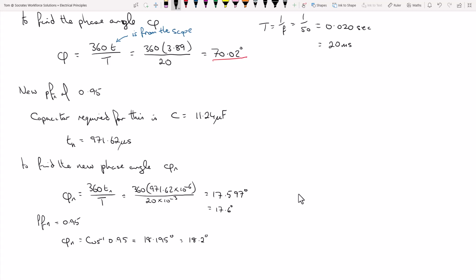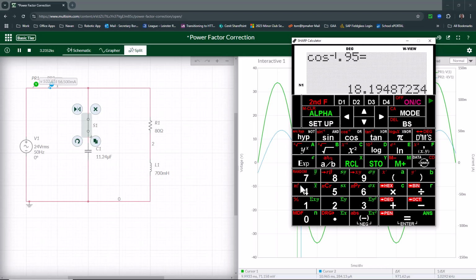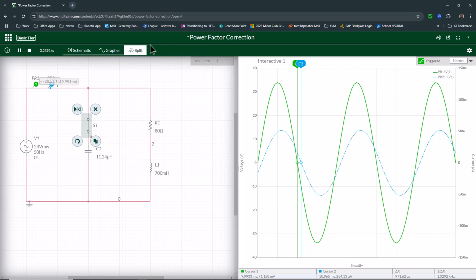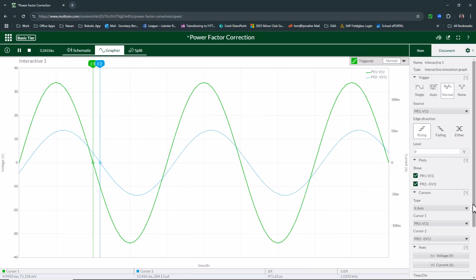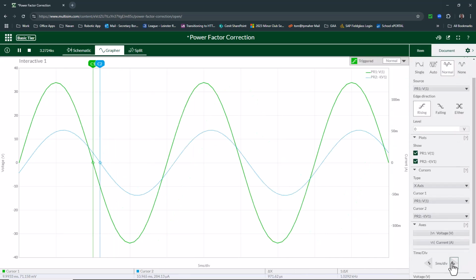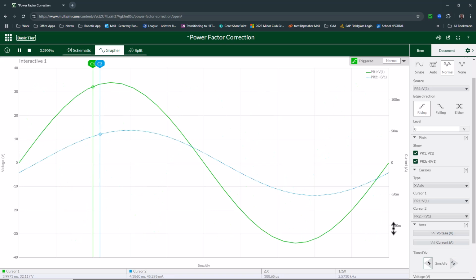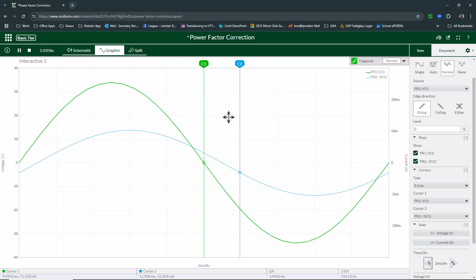Okay, what can we do to improve that a little bit? What we could do is go back here on the grapher screen, put up the properties, and bring out our time base a little bit. So we can do that now, and move the cursors again, and it might give us a little bit more accuracy this time. We might be able to snap a little bit closer. So 71 millivolts is as close as I'm getting there.